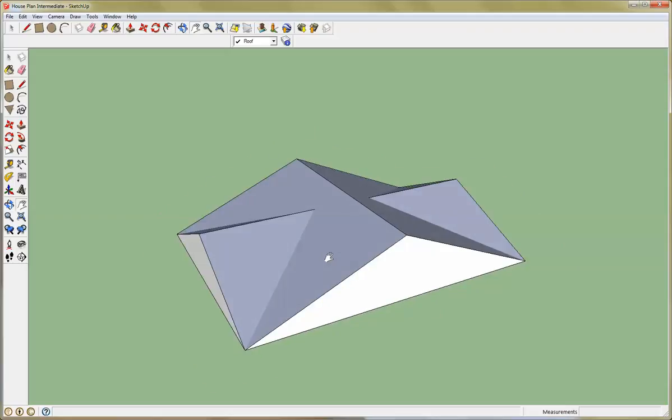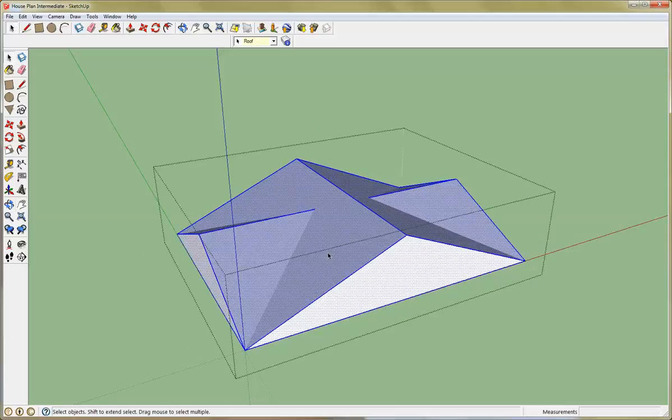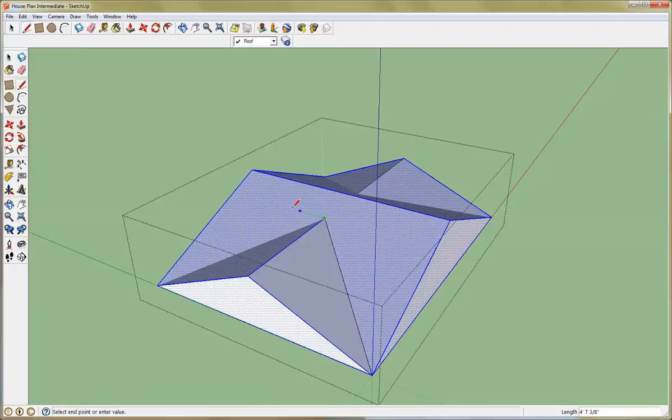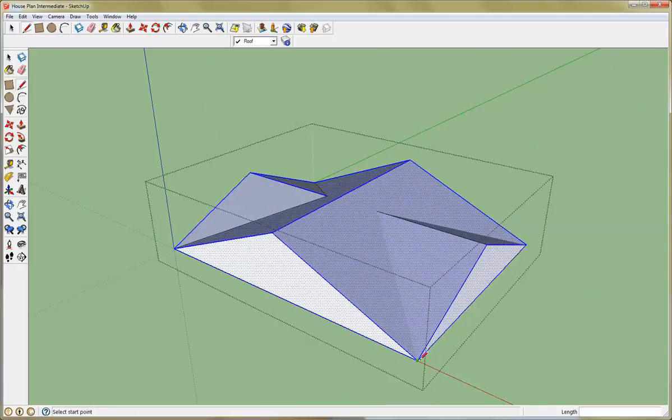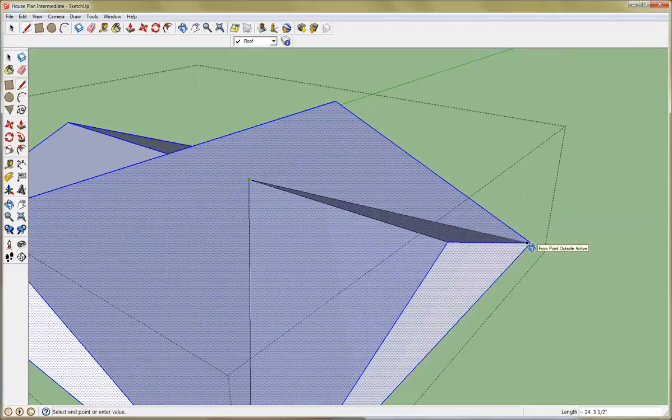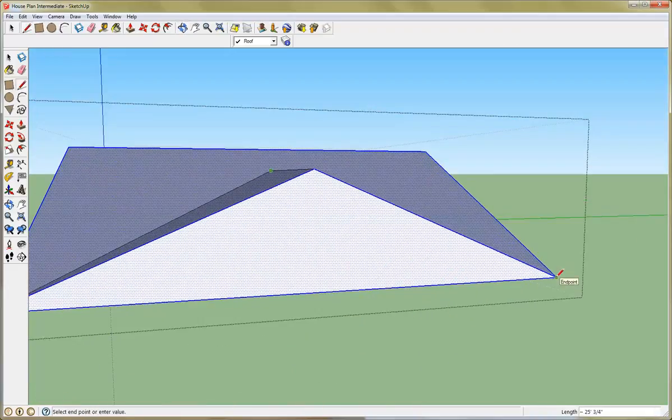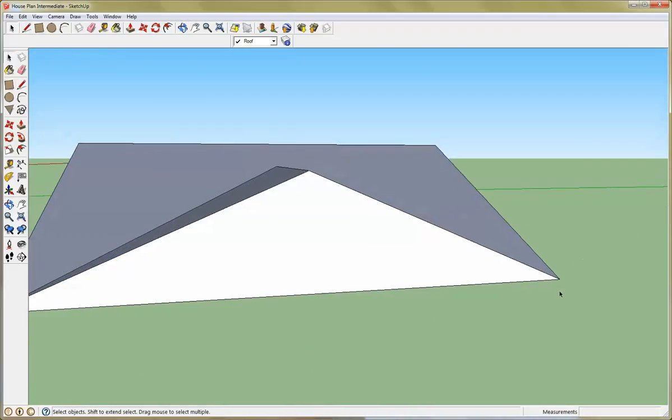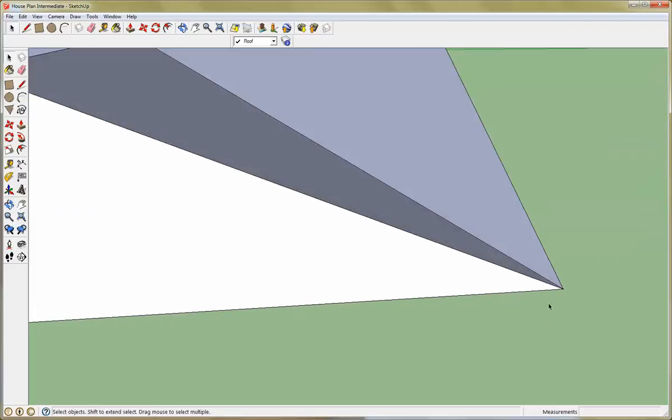And so to finish this roof, we'll triple click in. We've got to add the valley lines. This is the valley here, up to the top. Continue the line down. Here. Spin around the other side. Up to the valley top here. Up to the top. Continue the line down. All the way down. Make sure you're not stopping short of the point. Make sure you're going all the way down to that lower corner.